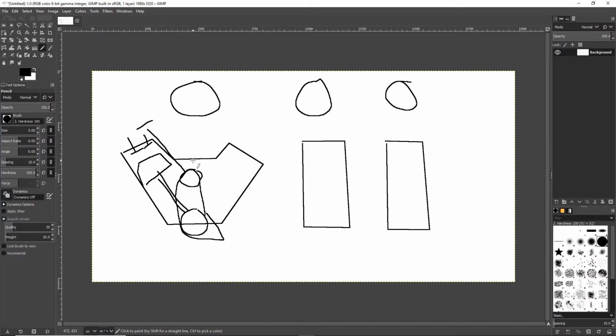So this was great, but in order to have enough lobes on the camshaft to open these valves, the best I could get away with was one intake valve and one exhaust valve. And the intake valve is always bigger, always, always, always, than the exhaust valve, no matter what engine you ever look at. And look how much dead space we have in the cylinder that we're not using. So you don't hardly ever see this anymore. Just about every engine has moved away from this. But if you hear the word pushrod engine, that's what this means.